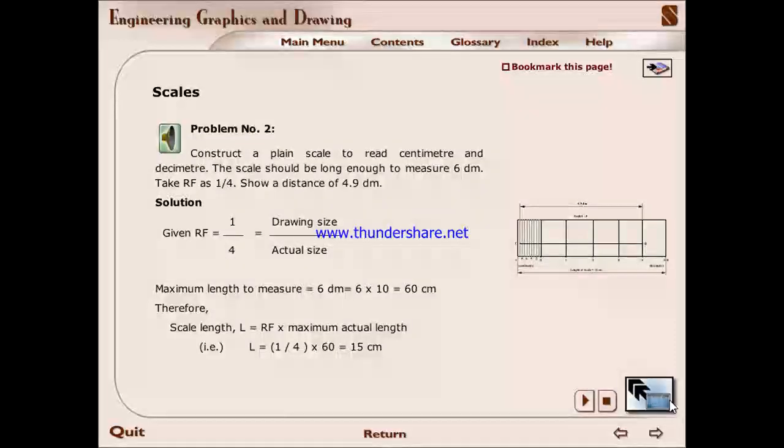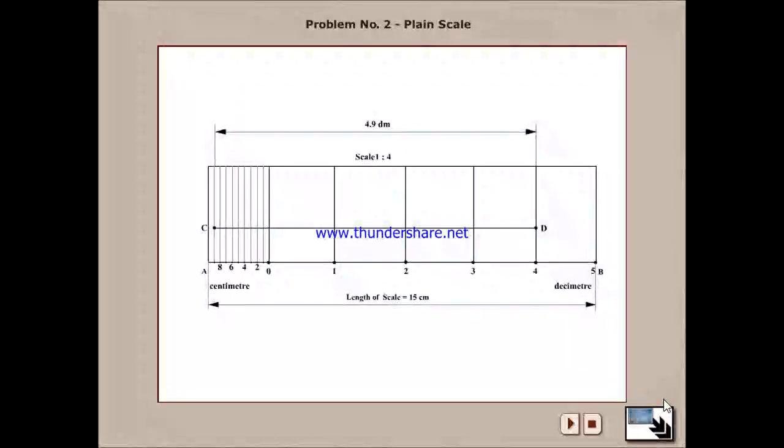Problem number 2. Construct a plane scale to read centimeter and decimeter. The scale should be long enough to measure 6 decimeter. Take RF as 1 by 4. Show a distance of 4.9 decimeter.